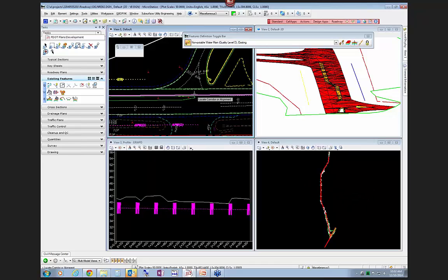But once you select the view cross section tool, it asks you two things: select a corridor or an alignment. Since I didn't create an existing corridor of the whole existing baseline, this whole existing US 98, then I'm just going to select a baseline that's in the topo file. All right, now this is something I just want to point out.